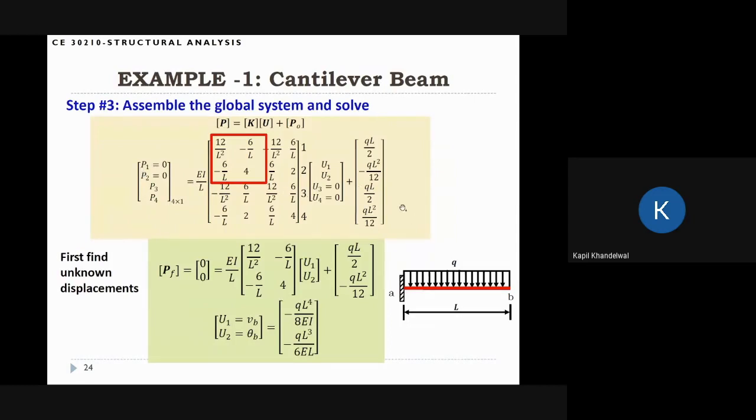And so if we try to solve the system, what's going to happen? We have to solve for just U1 and U2, but make sure that you include the P0F vector here. So P0F is these first two numbers. So we just solve for U1 and U2 in this system. And if we try to solve for U1 and U2, I'm solving here symbolically using symbolic algebra. So these are the numbers I'll get.